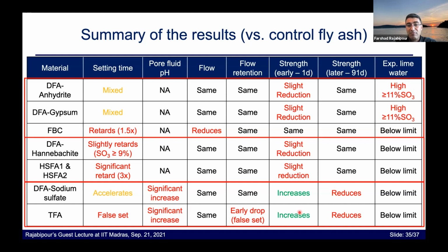They generally give you some benefits in terms of early strengths at the cost of a later age strength, which again can be designed for by tweaking the water cement ratio and things like that.